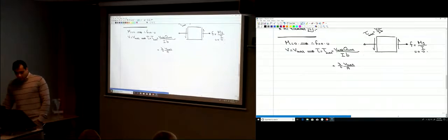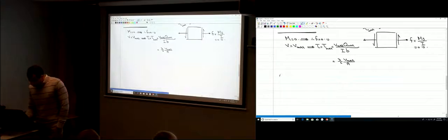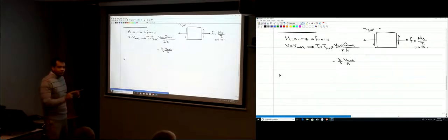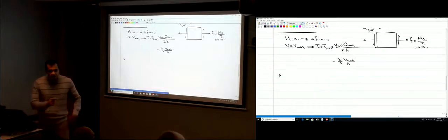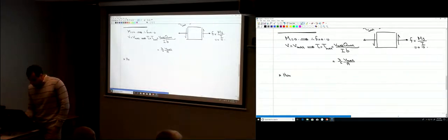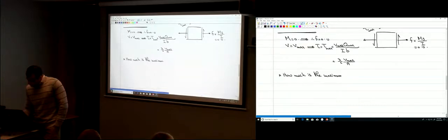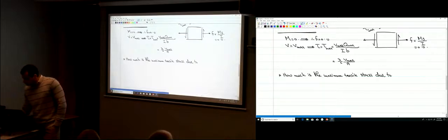So now, the question is, I don't care about the shear stress. My problem is not the shear stress. What's my problem? My problem is the tension that results from this shear stress. So how much is the maximum tensile stress due to the given stresses?